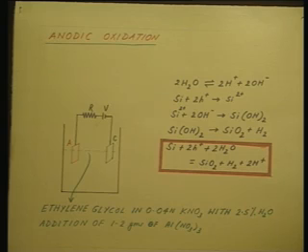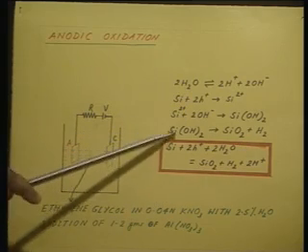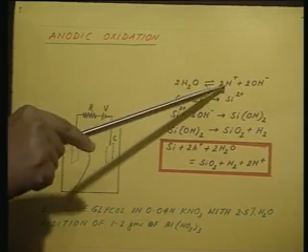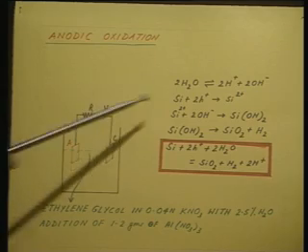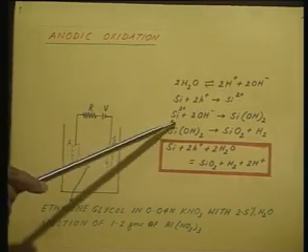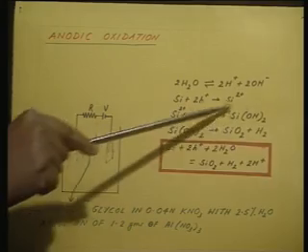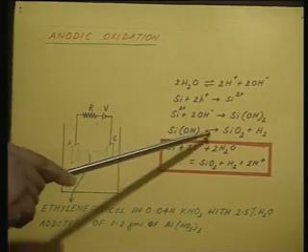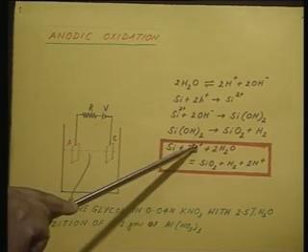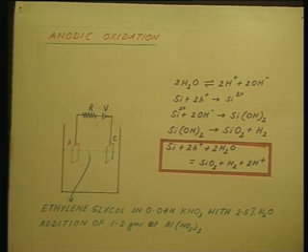And this is the basic reaction that takes place. This is the overall reaction. There are a number of sub reactions. First of all, water molecule is electrolyzed into hydrogen and hydroxyl ions. Then silicon with 2 holes forms Si2+ ions. Then this Si2+ reacts with the hydroxyl ions to form Si(OH)2, and then this Si(OH)2 dissociates to form silicon dioxide and hydrogen. So, the overall reaction is silicon plus water plus holes forming silicon dioxide plus hydrogen. This hydrogen is evolved at the cathode. You can see bubbles of hydrogen gas forming at the cathode.